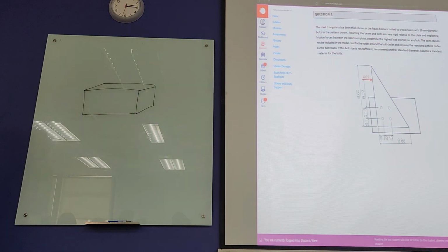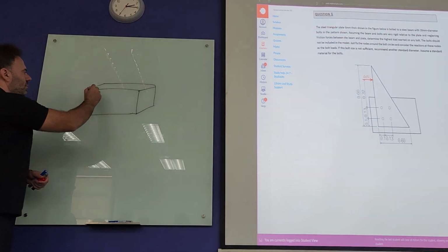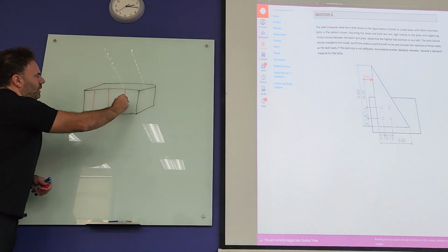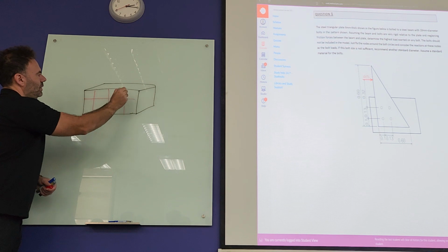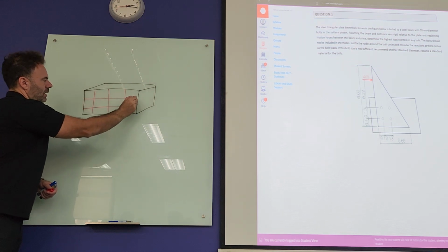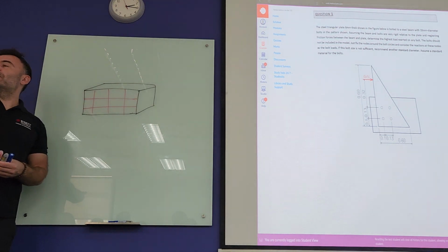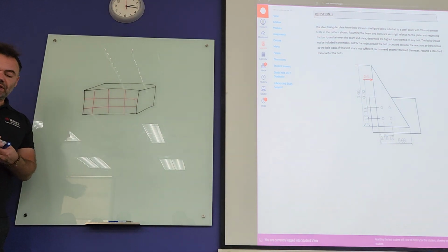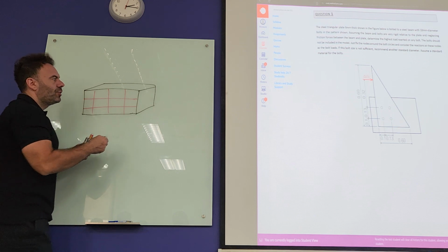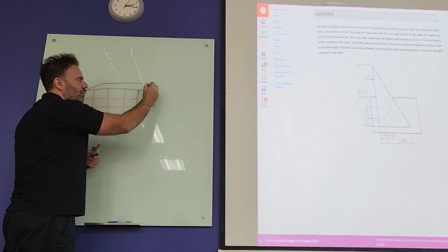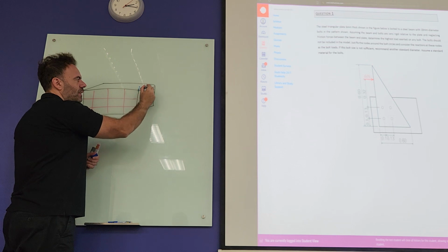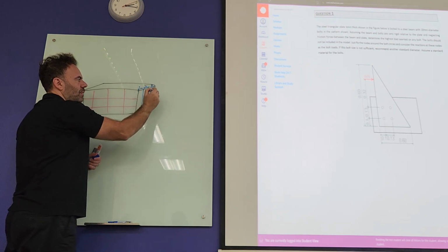Now, I don't know how many elements are going to be here. If you use 12 elements to measure the front face, then to capture what happens through thickness, you should at least have 3 elements through thickness. 1, 2, 3, in that direction.